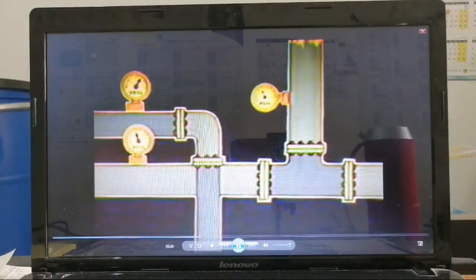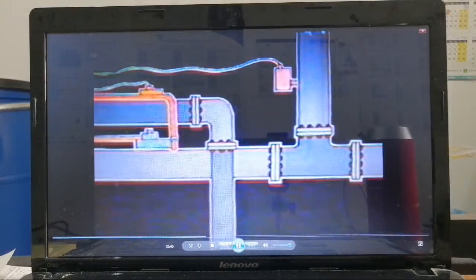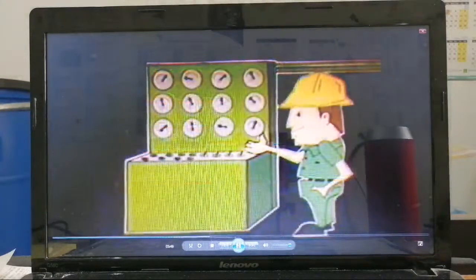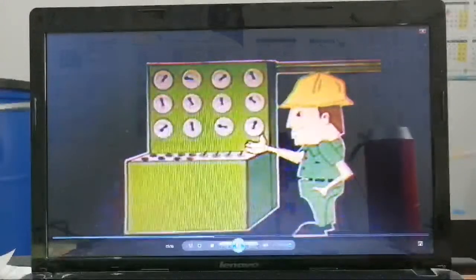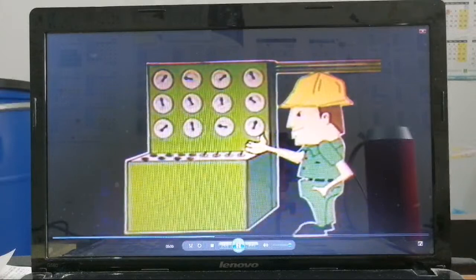Manometers, bellows gauges, or Bourdon tube instruments all read pressure where it's measured, sometimes quite a distance from the operator. So, we use devices which are able to convert electric voltage or pressurized air to a signal based on its own reading. This signal voltage or pressure is transmitted by wires or small tubes. At control or instrument stations, these transmitted signals are displayed for the operator. These same signals may also be used to operate other control devices which hold pressures within proper ranges.